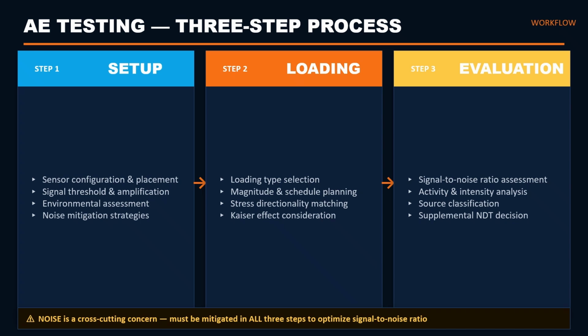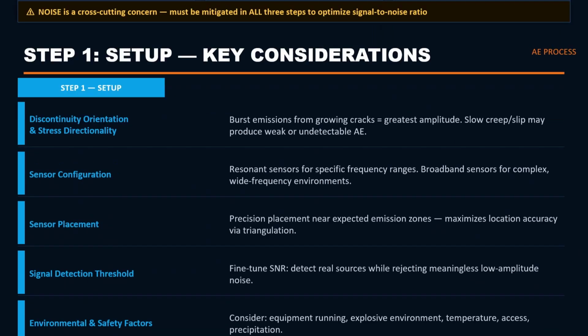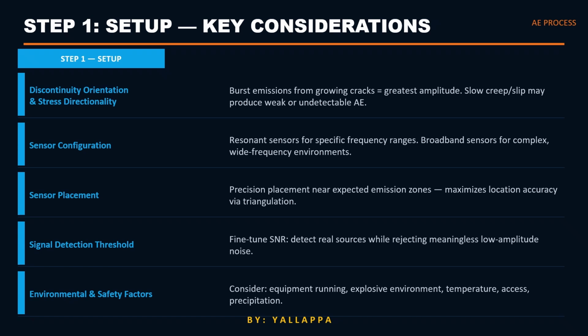Then comes step 3, evaluation. This is where the Level 3 professional analyzes density, waveform behavior, and source classification, and finally decides whether supplemental NDT is required.